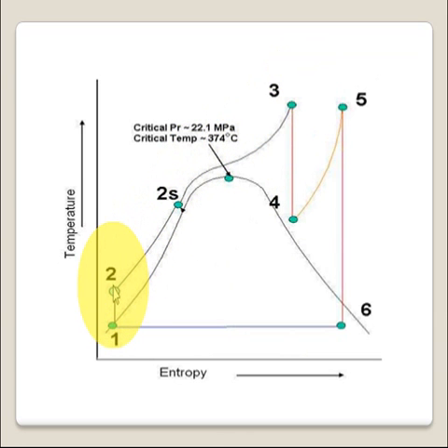In this case, the liquid is heated up to 2s or some point, and after that, the liquid is directly flashed into steam without absorbing latent heat. Latent heat is not required above the critical point because liquid is directly converted into steam. Okay, here when we heat the liquid along this curve, liquid is converted into steam without latent heat.